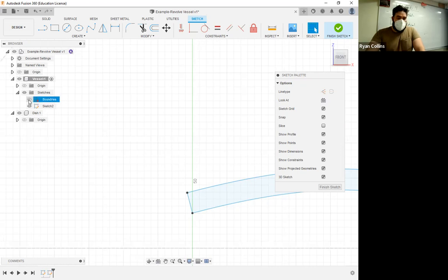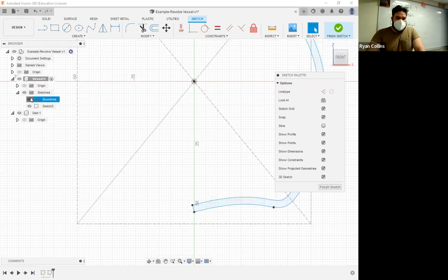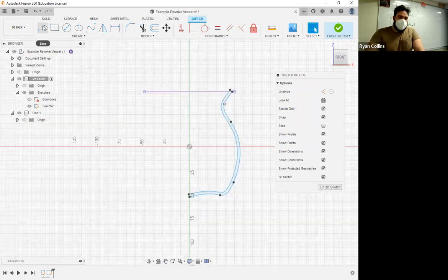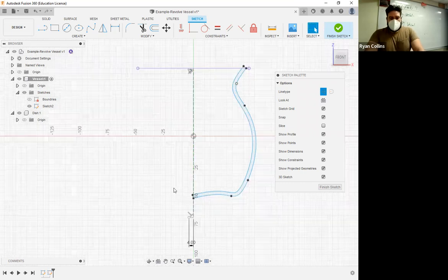So how can I change that? Well, let me unhide my first. That didn't help. I couldn't remember if there was a vertical line there or not. All right. So I'm going to start a new line, but I want this to be a construction line. I don't want it to have much of any effect. I'm just going to go draw from the top. And remember, when you mouse over something, the little triangle that shows up is the middle. Straight down. Whoop. All I want, just that line.